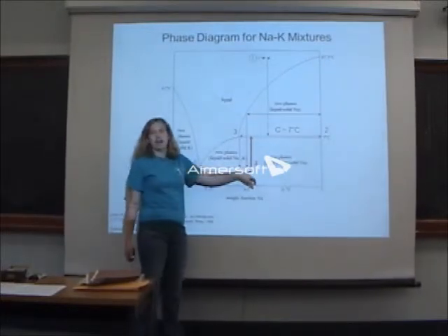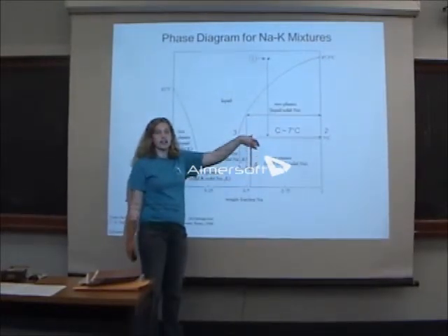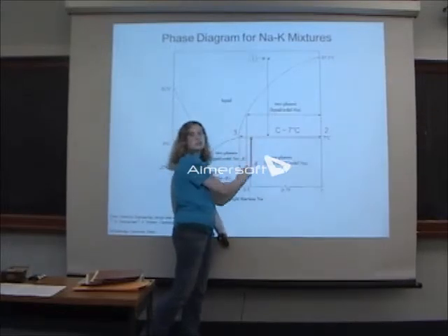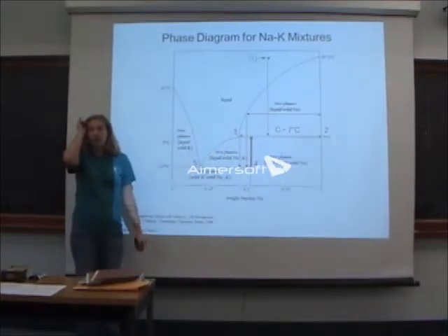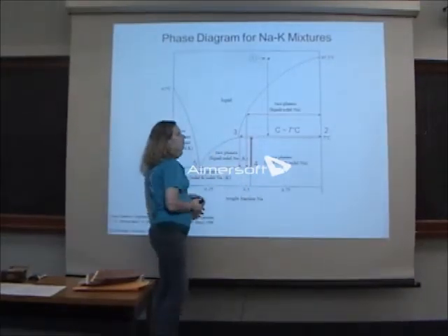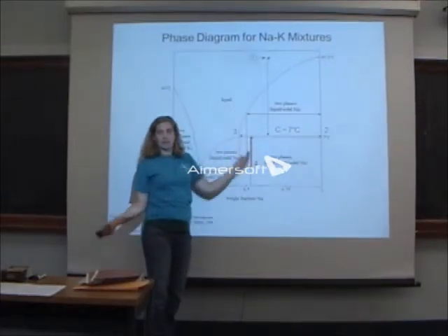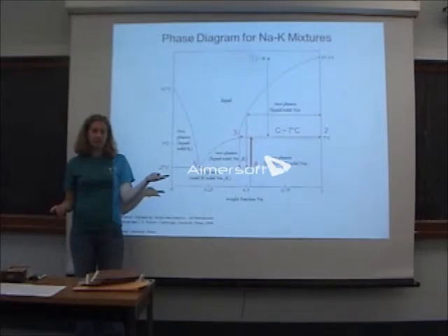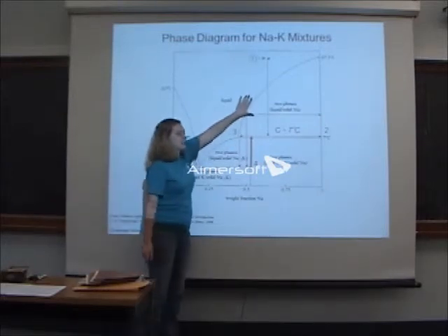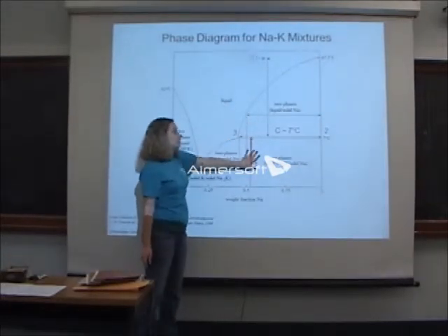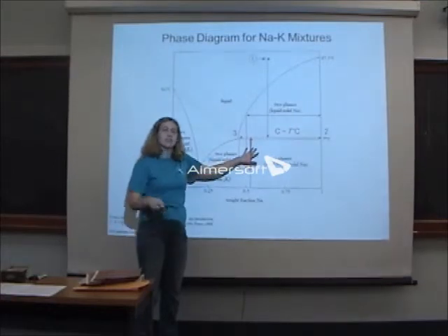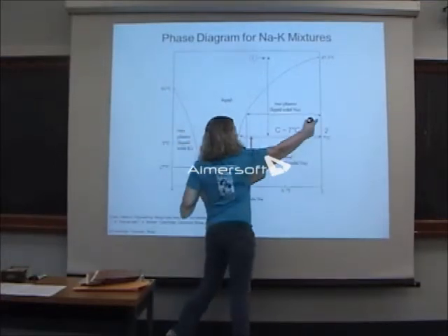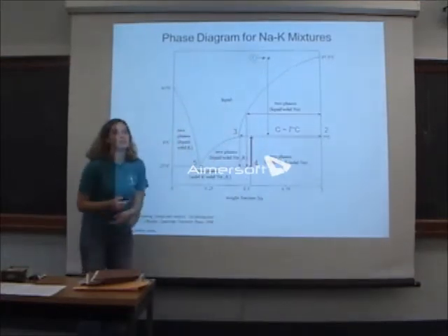But what am I doing with that? Just recycling it. So basically this recycle is becoming really big, right? That recycle is becoming really big. But what would be the benefit of this? I get to operate at around 20 degrees Celsius. I only have to buy 1 cooler instead of buying 2. So I can take this to 20 degrees. My recycle becomes bigger, but because of an overall mass balance, my 2 outputs stay the same.